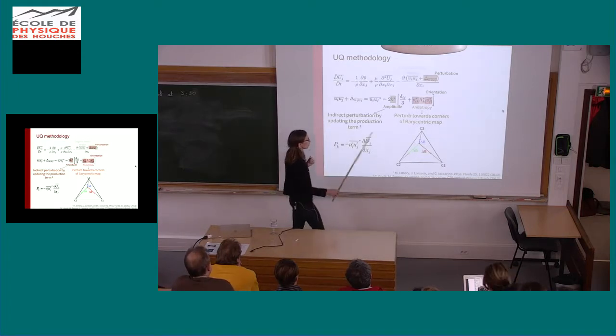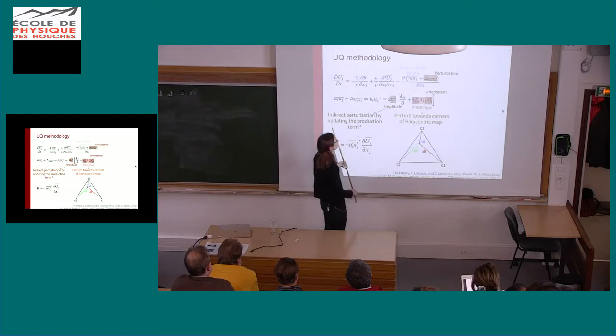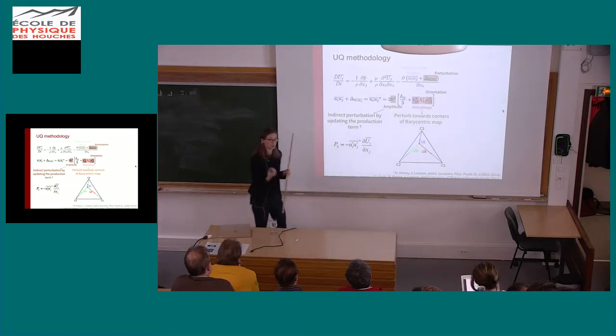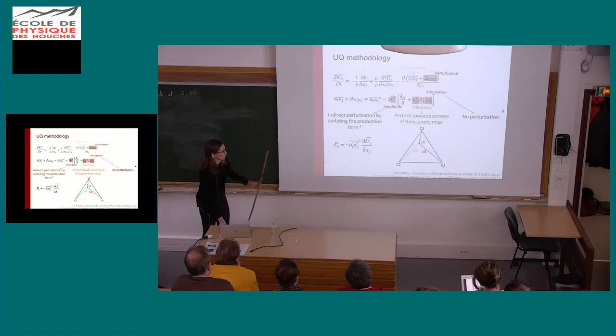You can also show that in terms of the orientation, if you go to C1 and the rate of strain tensor and the Reynolds stress tensor are aligned, you really get the maximum production of all. So we can keep our original model alignment to look for maximum production, and we'll get 0 production in the isotropic corner without doing any changes to the orientation as well.